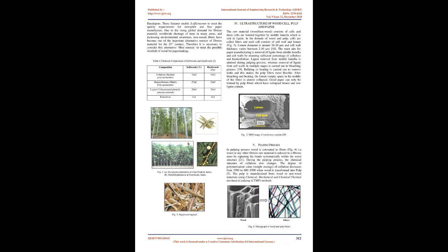Fig. 3. Greater opacity, absorbency, and dimensional stability were observed in pulps made from these species. Chemically, both eucalyptus and subabul wood species have closer percent of A. Acid insoluble lignin, eucalyptus 27.9, subabul 24.3, B. Percent of holocellulose, eucalyptus 70.3, subabul 75.2, and C. Percent of ash content, eucalyptus 0.66, subabul 0.65, as per the report published by PRI, India.